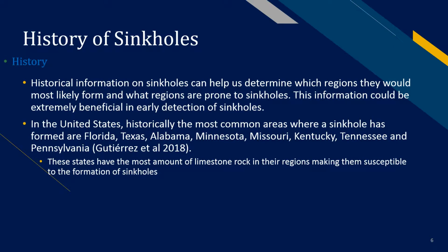It's important to know the historical background of sinkholes in an area. This allows you to plan where you're building your projects to make sure that you're not going to build on an area that's susceptible to sinkhole catastrophes. In the United States, the historically most common areas of sinkhole formation are Florida, Texas, Alabama, Minnesota, Missouri, Kentucky, Tennessee, and Pennsylvania. Just about any place that has a limestone bedrock base and high amounts of water is going to be an optimal zone where you're going to see a lot of sinkholes.